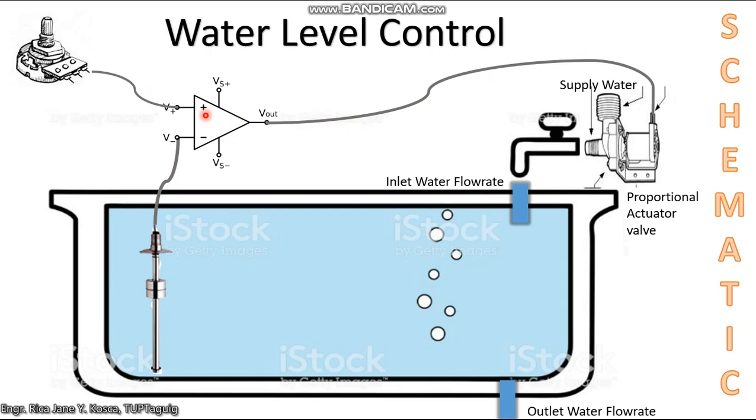Okay, so the 2 millivolts difference will be amplified, let's say a gain of 1,000. So the 2 millivolts times 1,000 will be 2 volts, no? At sabihin natin, for example, that 2 volts is enough to drive this proportional valve actuator.